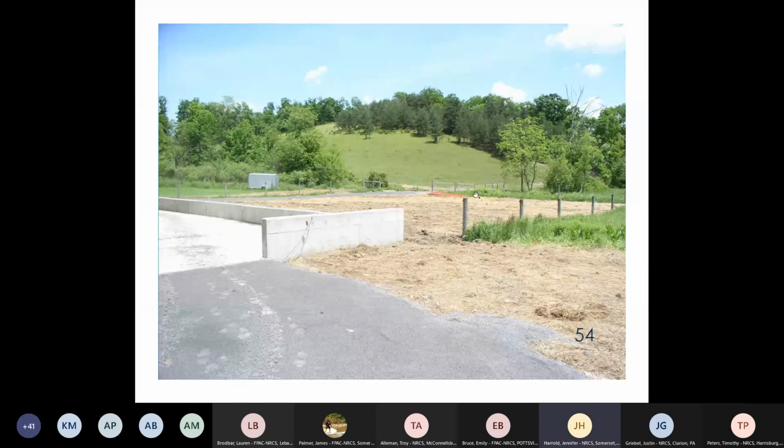They have access to multiple acres. Here, this isn't quite finished, but the feed would be placed on this concrete pad. This is a slotted curb where this is going to be maintained in grass vegetation. The cattle will not be on there. They'll be fed on this pad, and the manure-laden runoff will go through the slot and go through the filter area.